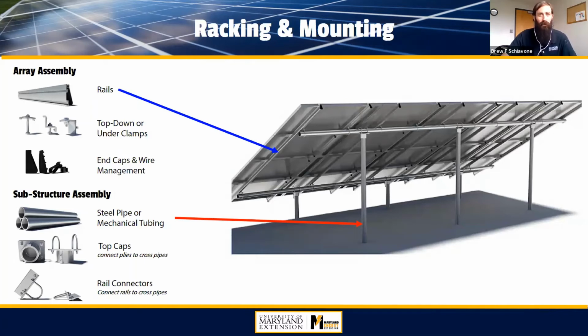This one's showing again the steel pipe or mechanical tubing, and this is driven into the ground, typically cemented in a footer. And then again, that tubing is the vertical and the horizontal support. You also have a railing system, and this is typically what you're buying specifically from a solar manufacturer. And so this railing system is going from the higher beam down to the lower beam. And again, that's what the modules are mounted to. So just to give you an idea of what some of these systems might look like, we'll go through an actual example momentarily though.